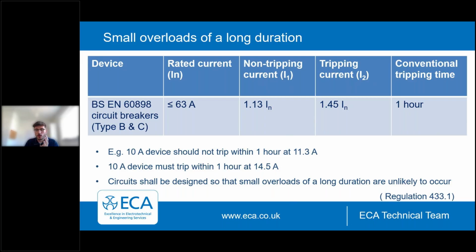Of course, we accept that overloads may happen from time to time. We've only got to consider when we initially switch some equipment on, but we should avoid this where possible as part of the circuit design, and we certainly need to avoid it for long durations. Now, the term long durations, I'm not aware of a definition for this, but from a bit of reading, and I know that the IET design guide refers to this, it is likely to be classed as a duration in excess of the conventional time.